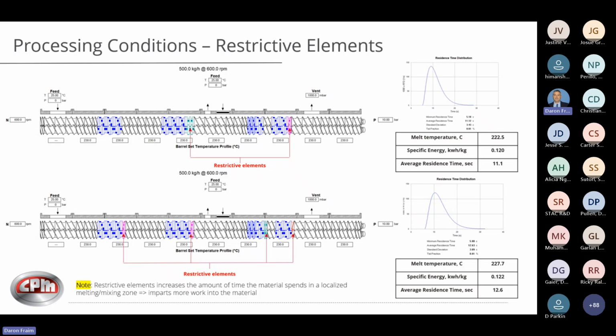My reverse kneading is forcing the material back upstream, so it's going to be more restrictive. My reverse conveying, remember, has a solid flight all the way around 360 degrees. There's no gap or spaces like the kneading blocks have, so the leakage flow is forced to go over the flight between the barrel wall and the flight tip, so it is the most restrictive.